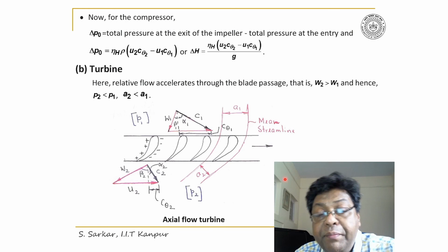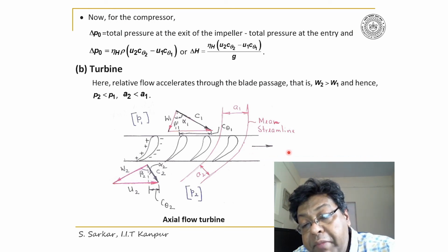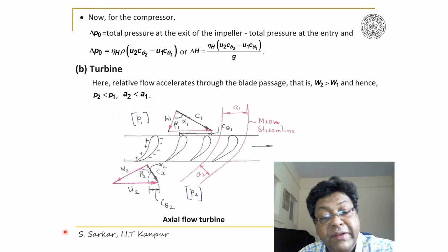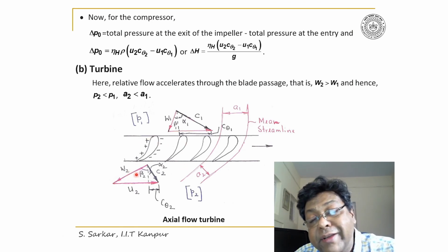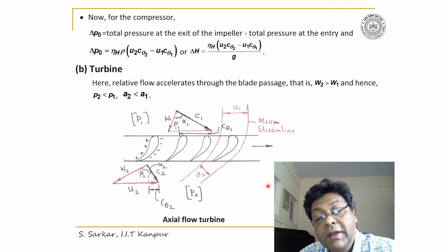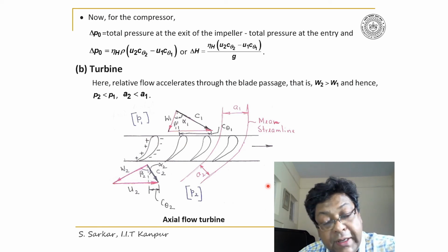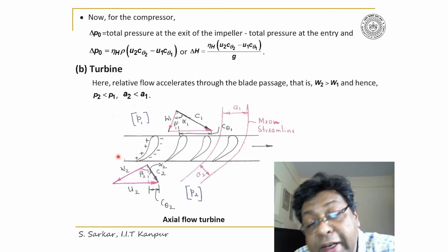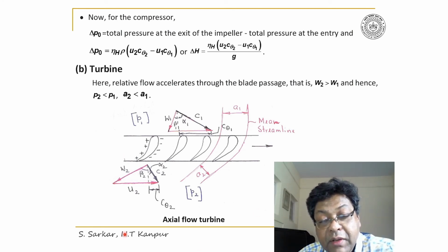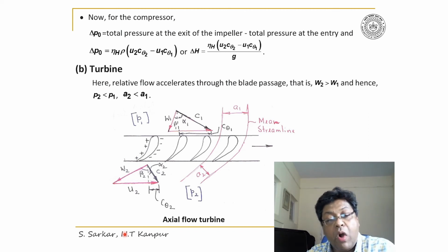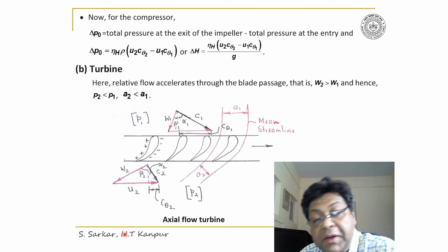And look, I have maintained the direction of rotation the same as before. Now you will find the pressure and suction surfaces aligned in such a way that the pressure surface will dictate the rotation. Thereby you can appreciate that you will get work output from a turbine.